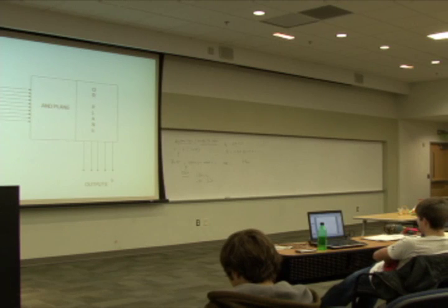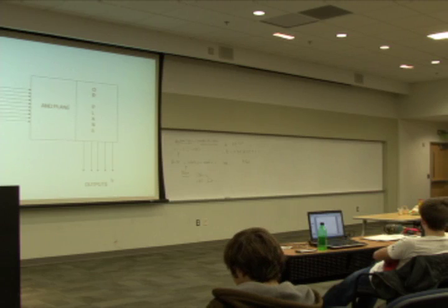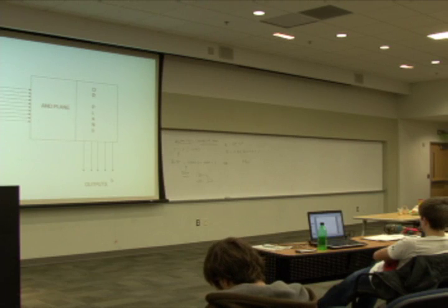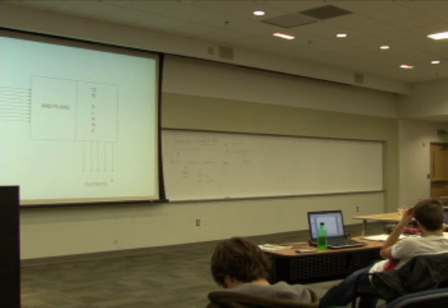So you can program it on the fly, and so now one of the nice things is that earlier I said these are discrete logic gates, and this results in a random logic design, a hardwired design, hard to debug, and so on. But now what I'm saying is all of that can be put inside a single chip and can be field programmed, which means that it is much simpler in terms of maintenance. Just as microprogram was simple to maintain, this is also becoming easier to maintain once you adopt this FPGA technology.